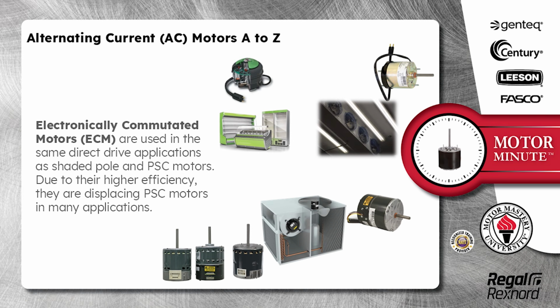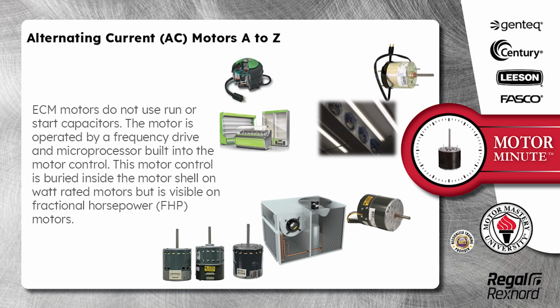Electronically commutated motors, ECM, are used in the same direct drive applications as shaded pole and PSC motors. Due to their higher efficiency, they are displacing PSC motors in many applications. ECM motors do not use run or start capacitors. The motor is operated by a frequency drive and microprocessor built into the motor control. This motor control is buried inside the motor shell on watt-rated motors, but is visible on fractional horsepower motors.